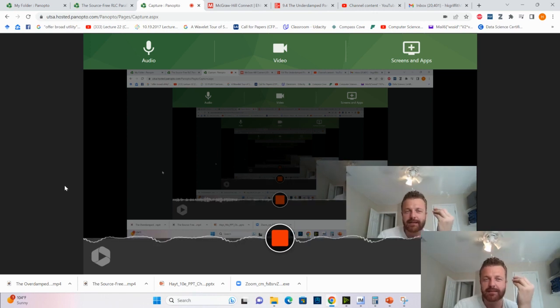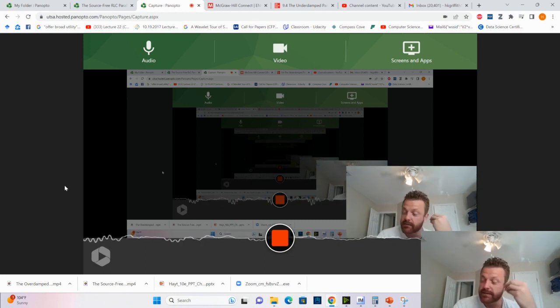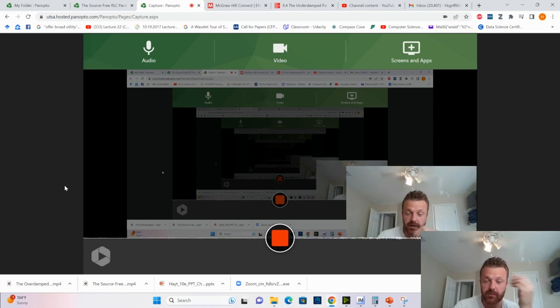And then really what I want to see is not necessarily you solve some kind of innovative out-of-the-box problem, but just be able to replicate that process and show step by step how the initial conditions are determined, how the characteristic parameters of the circuit are determined, namely the damping factor alpha and the resonant frequency omega naught as a function of R, L, and C, and how you find your initial conditions and use them to determine the unknown constants in the general response.